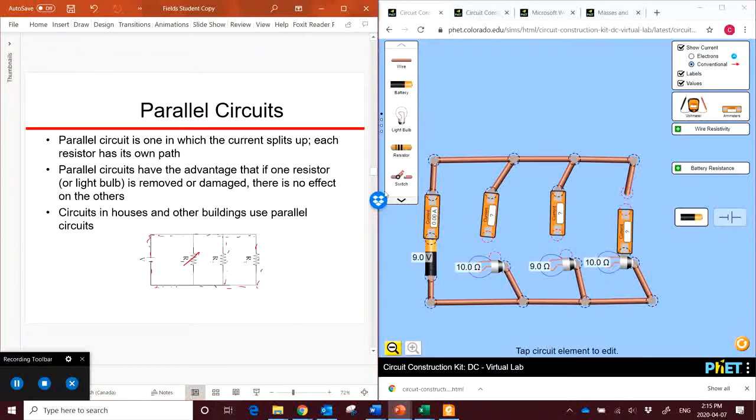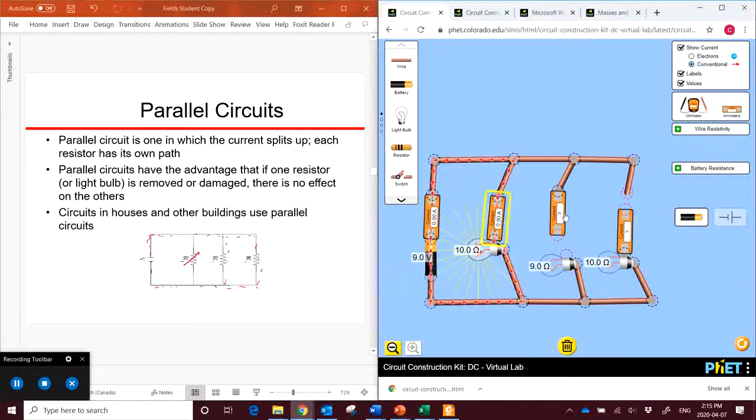So on the right here is the circuit I have set up. If we take the amp meter here and connect it in there, we've just created a simple circuit like we saw in the previous video, with just a battery and a light bulb. I have an amp meter set up at each location to continuously measure the current in each branch. So we have a normal circuit running, and the electrons again go from the battery through the light bulb and back again. The light bulb currently would be using the entire voltage, 9 volts, as the electrons travel through.